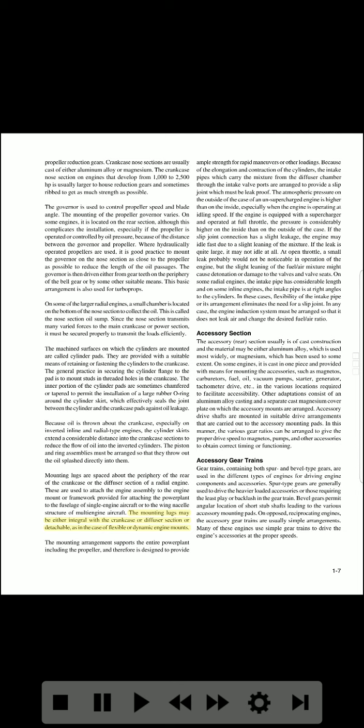As in the case of flexible or dynamic engine mounts, the mounting arrangement supports the entire powerplant including the propeller, and therefore is designed to provide ample strength for rapid maneuvers or other loadings, because of the elongation and contraction of the cylinders. The intake pipes which carry the mixture from the diffuser chamber through the intake valve ports are arranged to provide a slip joint which must be leak-proof.